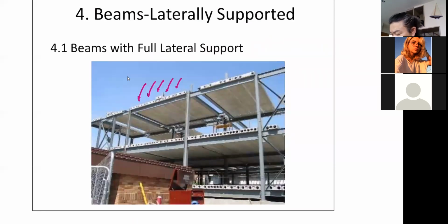This floor in turn will help prevent this beam from moving. You have to find a way to make sure that your floor will not move, in any way possible. When we do that, that action will also give us full lateral support for the beam as well.